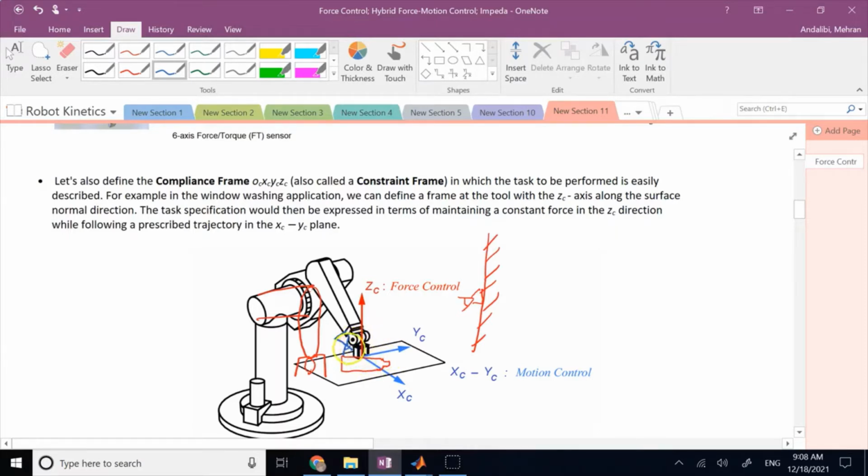You attach it to the end effector, but not exactly in the middle of the gripper. You put it at some offset distance and maybe a little bit of rotation with respect to the end effector to get the best visibility in all conditions. This one attached to the end effector, the robot in the hand, in the palm, gives you a lot better visibility compared to a fixed camera.